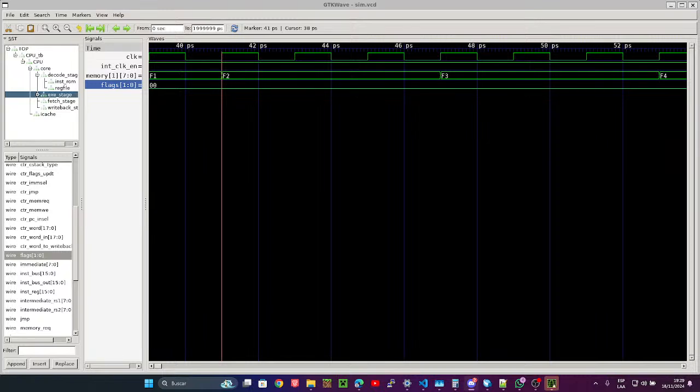Yeah, it's an exception, honestly. For bigger caches, I would need to consider the tags being in block RAM as well. Maybe for L1 we use registers, and then for L2 and L3 block RAM. Which, you know what that means?